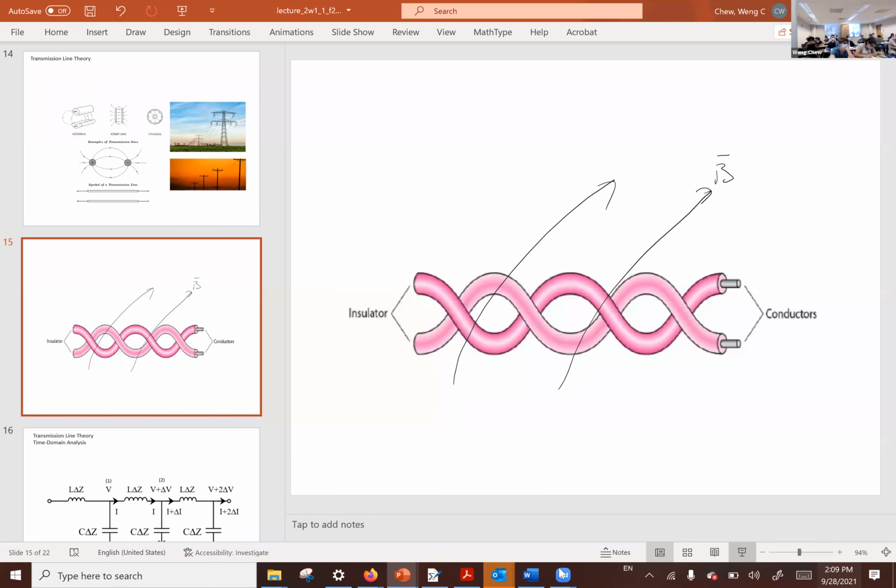And these are in the room. You will see that the magnetic flux will have flux linkage to this crossing wire. In opposite polarity, some of the loops will get a positive flux linkage. The other loop will get a negative flux linkage. So on average, the flux linkage is approximately zero, so a design like this picks up very little interference from the outside. It still comes up to the minimum. So we just use a very simple concept of Faraday to come up with this design.